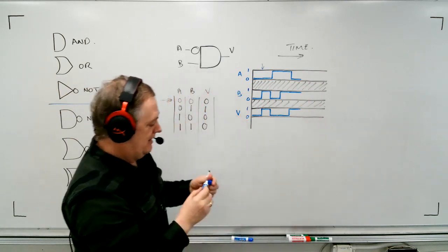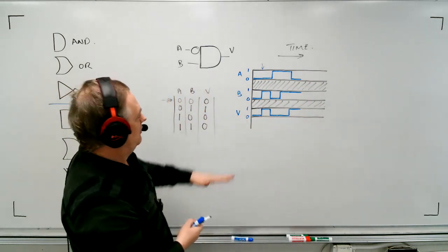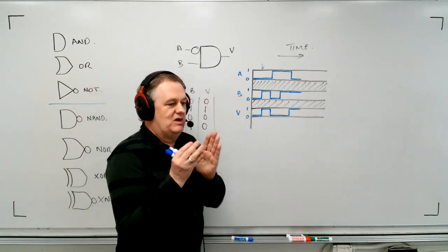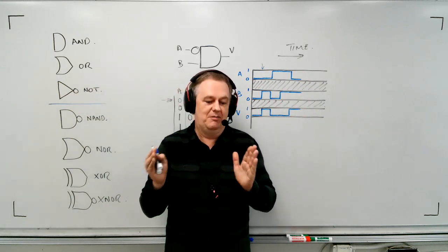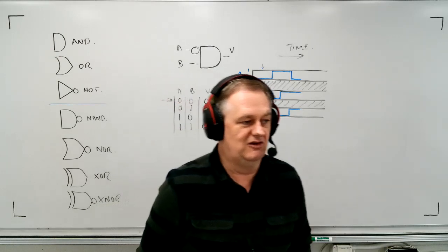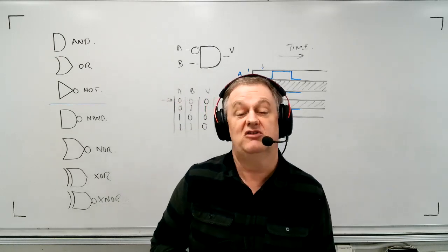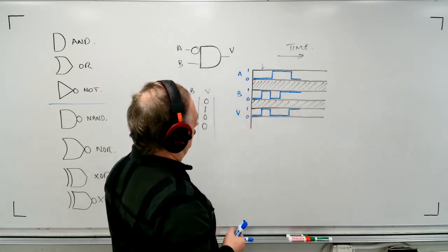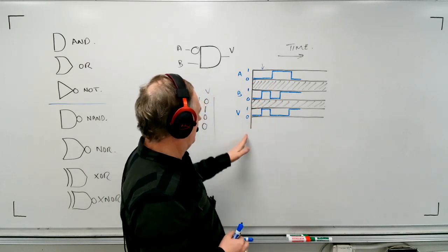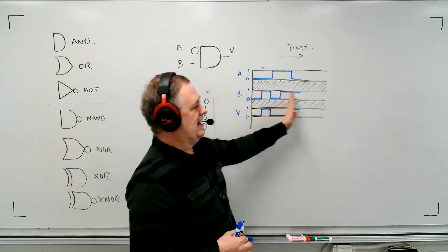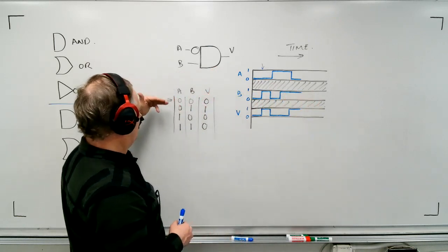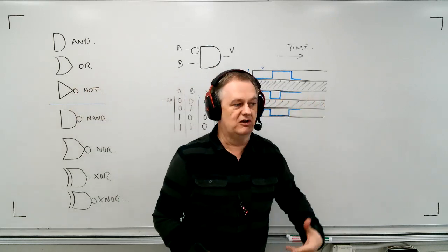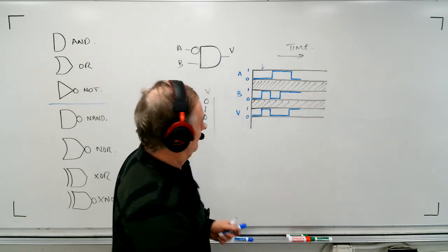These are called timing charts, and it's kind of function charts. These types of charts are often used because they show events as they move through time, what will happen. And these are often shown with relays to show what different modes of relays will do, especially timing relays. So it's very valuable to be able to look at this kind of chart and understand it, try to draw it out and understand what's going on. You're just really looking through time at these conditions, starting with one condition, moving to the next, to the next, and graphing it. So it's a graphical chart of a truth table, really.